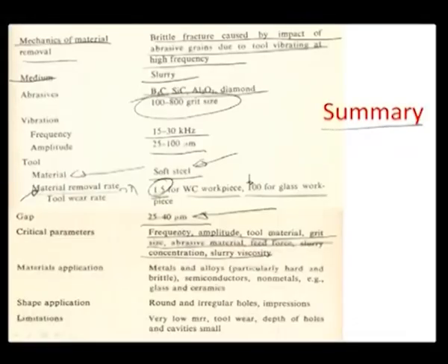It is a low yield process, with high tool wear, and of course you have a limitation in terms of the depth of cavity or the depth of holes that you can realize, although in microsystems that is an advantage because the cavity that you are looking at is actually close to some tens of microns in thickness. And so, this process is very well used in microsystems for doing active fabrication.